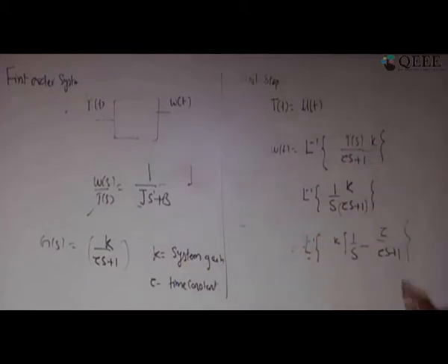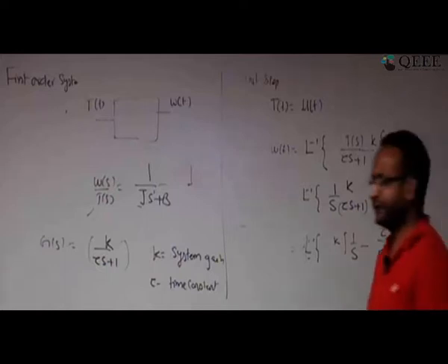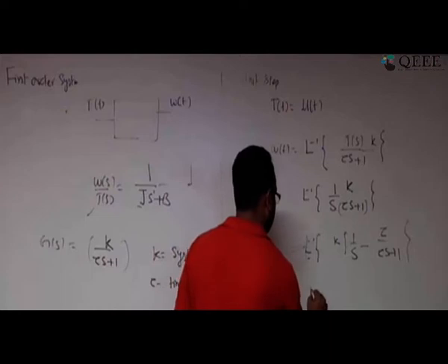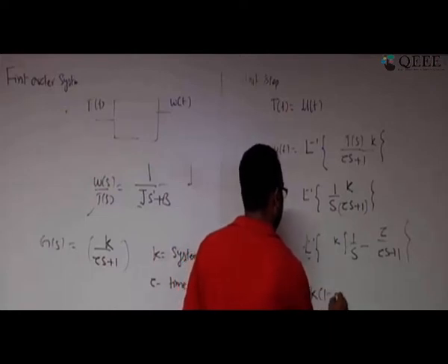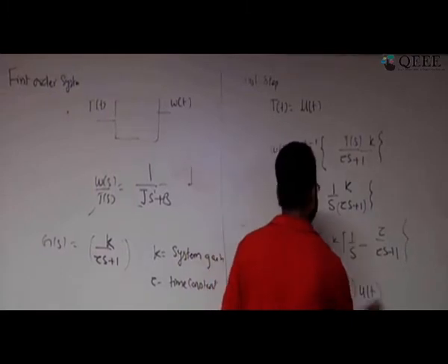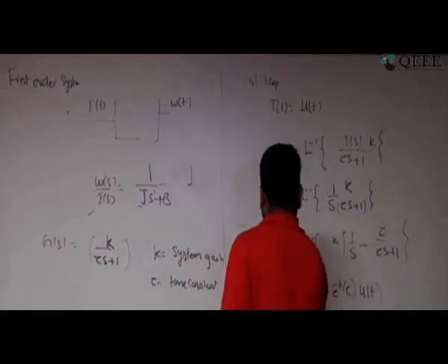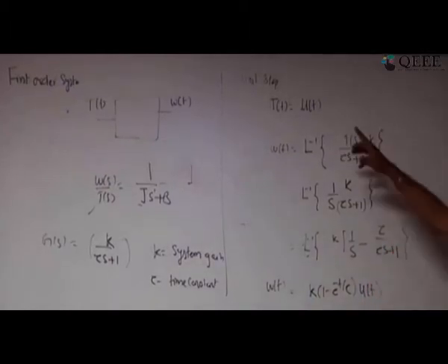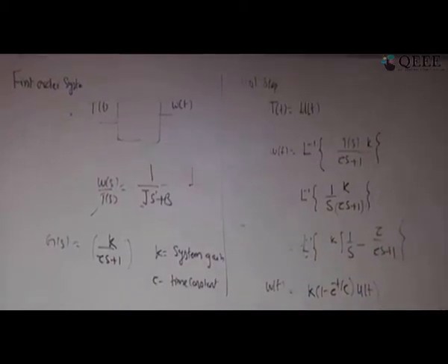You can check it. It comes out pretty well if you look at any mathematics book, where they solve the inverse Laplace transform. If I take the inverse Laplace transform, it's k(1 - e^(-t/tau))u(t). This is going to be your angular velocity. In this specific case, when you apply a torque as a unit step input, this will be the response.